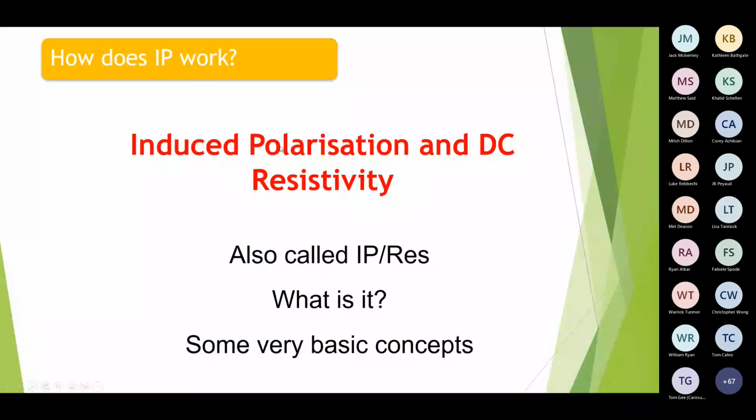This is an example of a DC resistivity survey trying to find hard versus soft rock from the perspective of building a road or something like that. And you can see here that the low porosity rocks like granites and a fresh basement are quite well defined by the resistivity in this saprolite zone. In this case, high resistivity is red. We geophysicists, to make it really lovely for you guys, randomly flip this colour scale for you. So sometimes red is low and sometimes red is high. You have to look at the colour scale because even I don't know half the time in my own reports. So you have to put the resistivity colour scale in there.